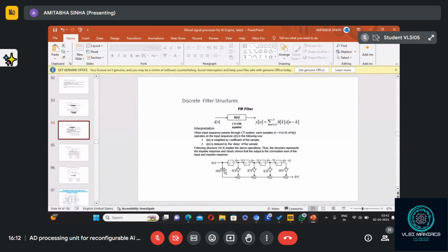There are two types of multiplications. One is when two time domain functions are multiplied, which is nothing but modulation. And the other is multiplication of a function by a coefficient, a constant. Here we require that because the Hks are constant impulse responses. Already we have shown that using switched capacitors, we can make such multipliers, we can make delays, and we can make these analog signal processing systems.